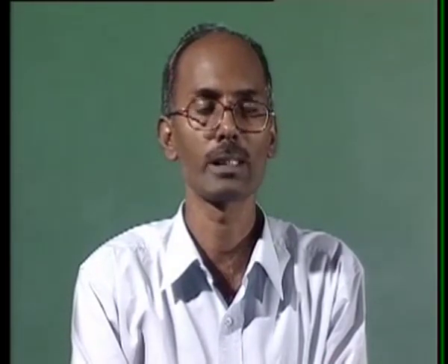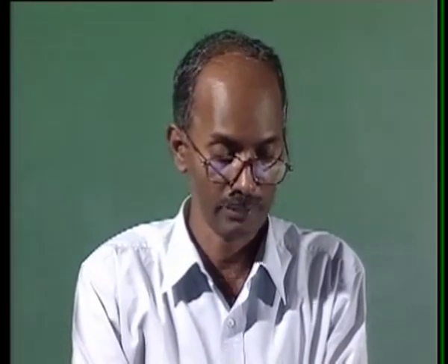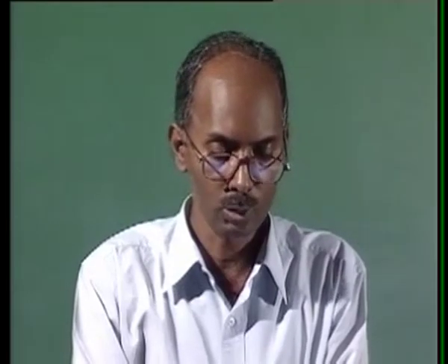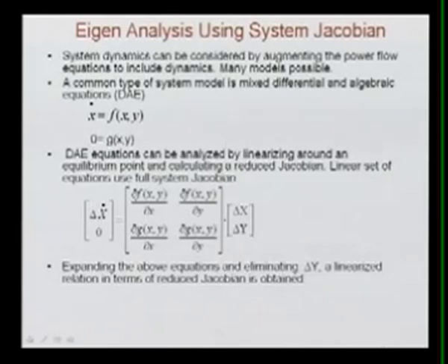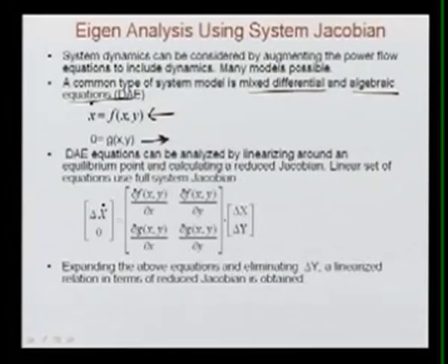Many models are possible depending on how many equations you use. We can write a common system model that is a mix of differential as well as algebraic equations. The differential part is the system dynamic model of generators, exciters and other load models, and the algebraic part is your power flow equations, which are your equality constraints.